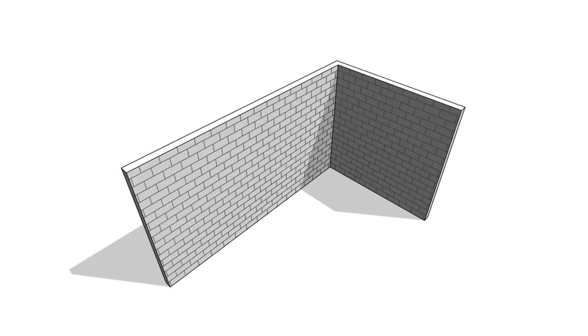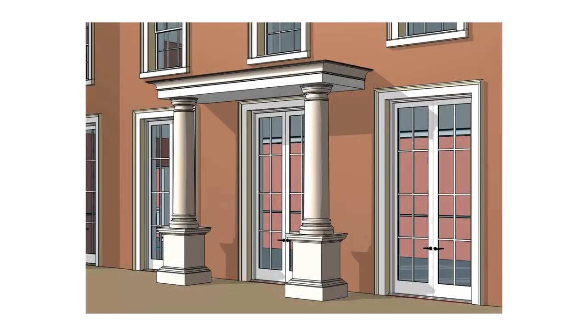In Revit, an architectural column will inherit the layers and finishes of the wall it is joined to. They are used to box out around a structural column that's built into a wall, or to create pillars in masonry walls where needed. The architectural column can also be used as the decorative encasing to a standalone structural column.